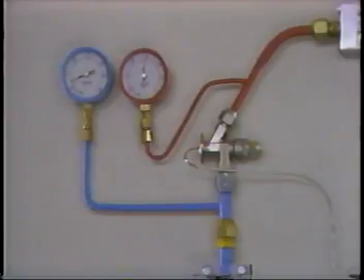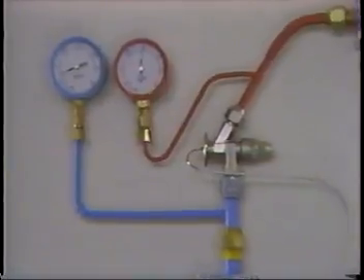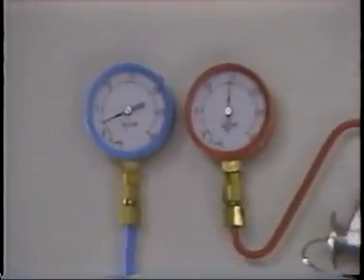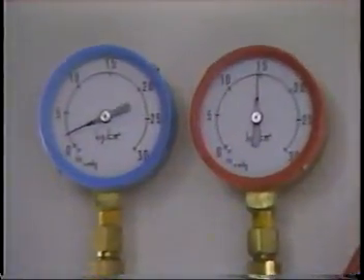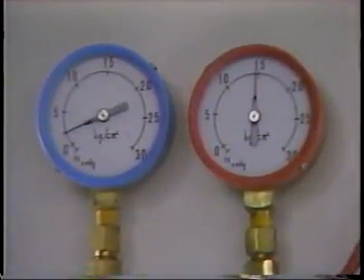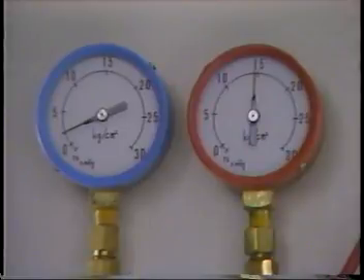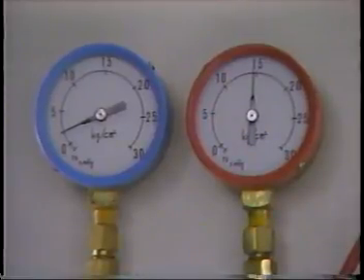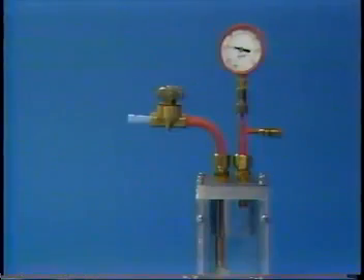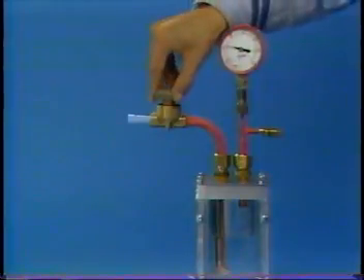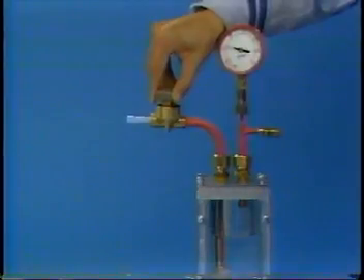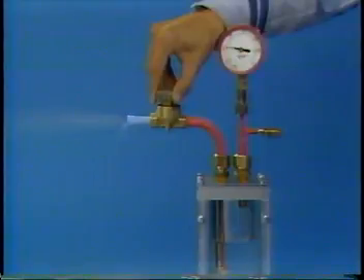Let's measure the pressure of the refrigerant before and after it enters the expansion valve. The refrigerant is sent from the compressor under high pressure, but the pressure is reduced substantially by the time the refrigerant leaves the expansion valve. The pressure is reduced by the expansion valve so that the liquefied refrigerant can be changed into a gas by the evaporator. At the same time, the expansion valve adjusts the amount of refrigerant to maintain the cooling capacity at an optimum level.